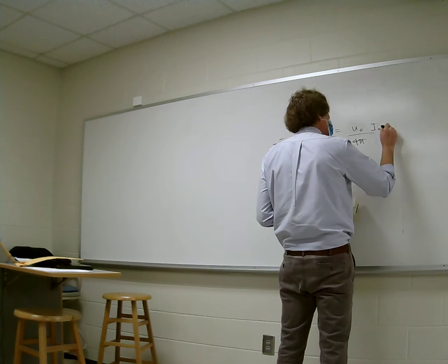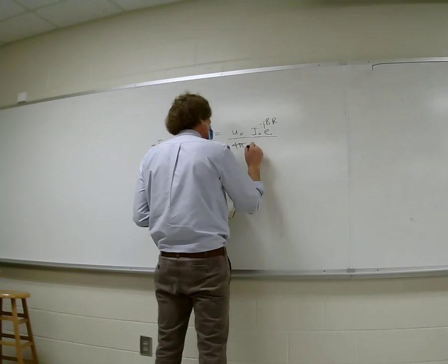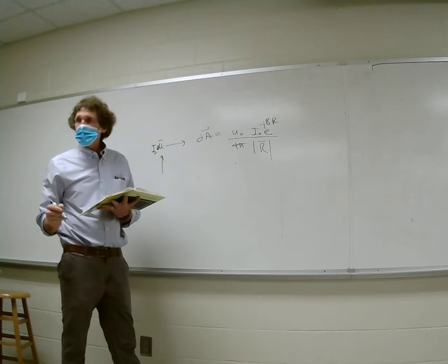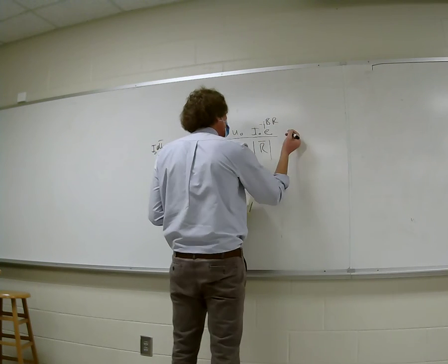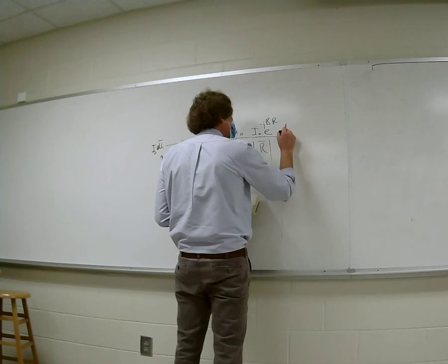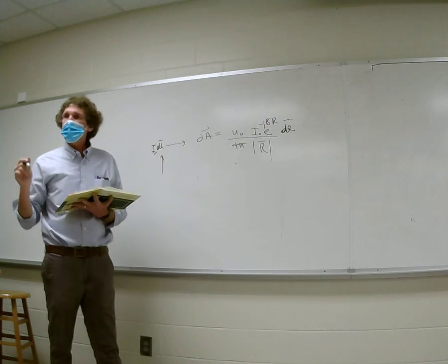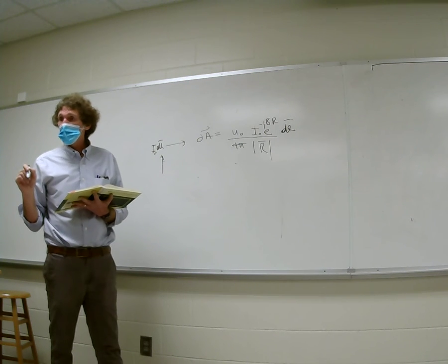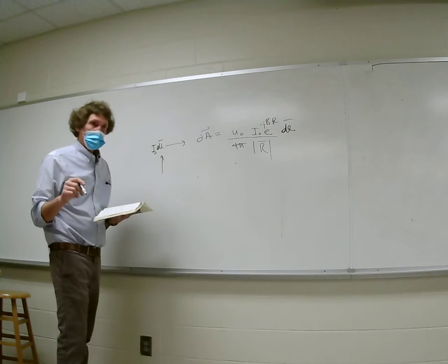I'm going to have e to the minus j beta r. R is the distance, divided by the magnitude of R. A lot of times they do that to show there's no vector sense there. Then it's going to be times dl, and I'll do it Wentworth's way, where Dr. Wentworth has a vector sense over there. So if it was a differential in the z direction, it would be dz az. That's what that vector sign means, okay? He has that. That's the differential A field.